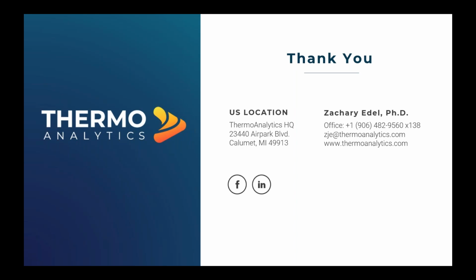Okay. Is there a way to simulate voltage ripple in the charging phase? Possibly. I mean, the electrical equation is transient for the NREL model. It does predict overshoot. It has a time constant, so when you apply a high current rate and then shut it off, you do see that the voltage overshoots the nominal value and continues going up before it drops back.